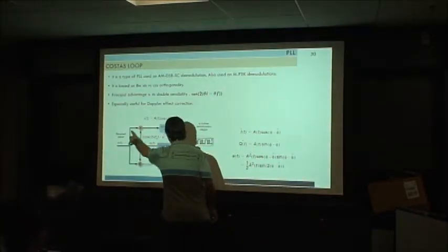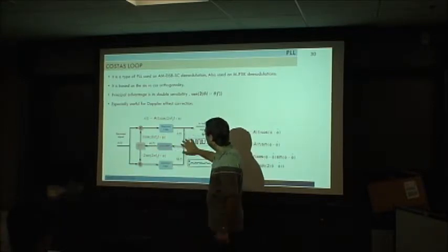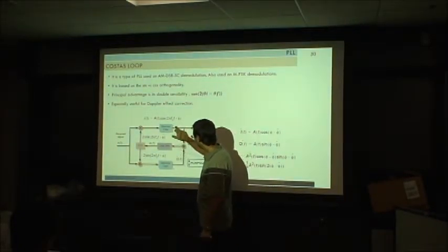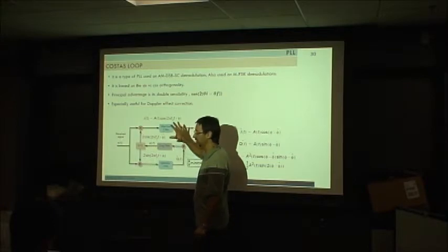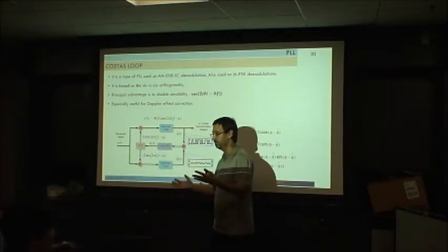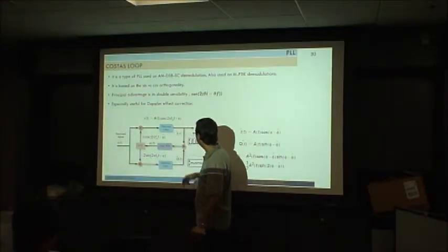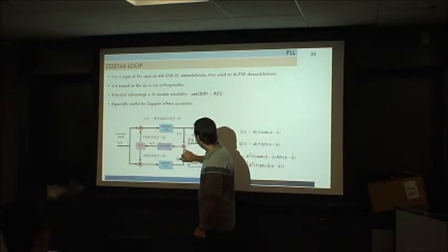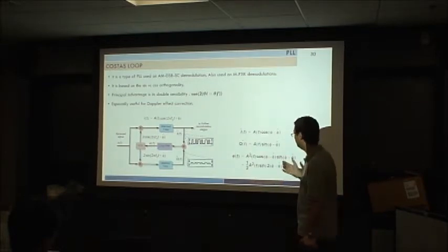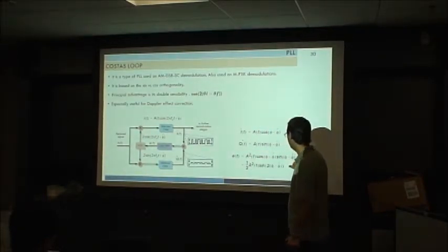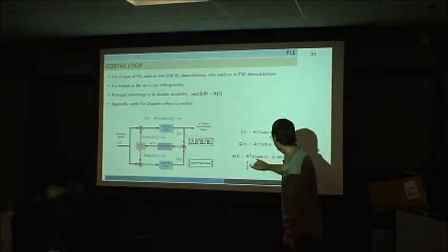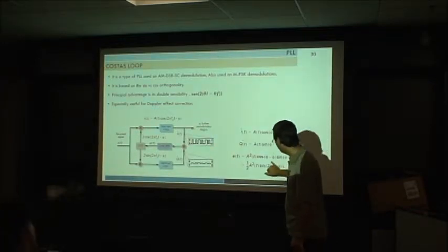You will have the signal coming here, the I and Q signal. And after this matched filter, or we call it the RC filter, there is something that is not shown, like the decision device, because as you can see this is an estimation. Is it 1 or is it 0? So some decision device should be there. Then you multiply these two signals, which will be I and Q after making the decision. If you multiply these two signals, it will give you something like this, and at the end, by a trigonometric identity, it is this.